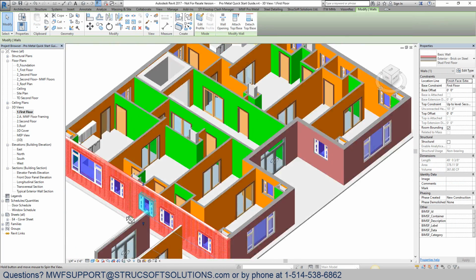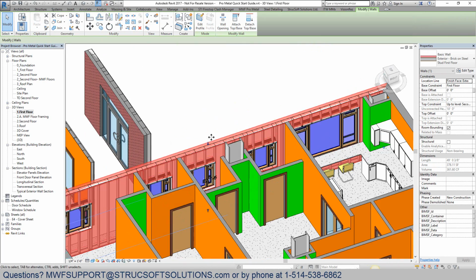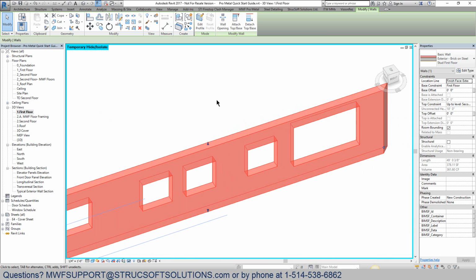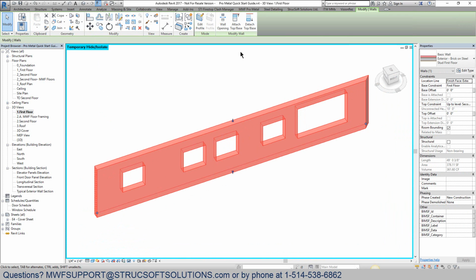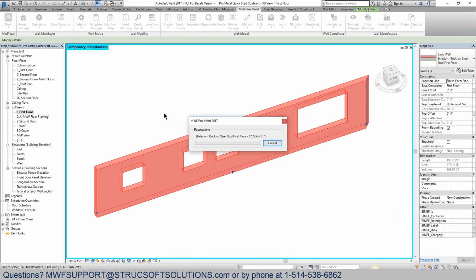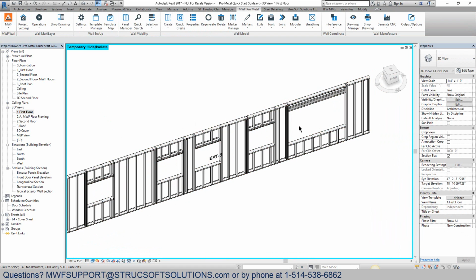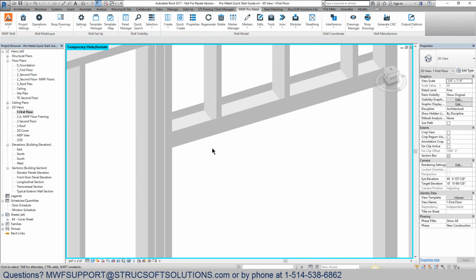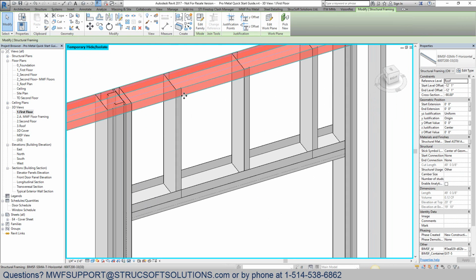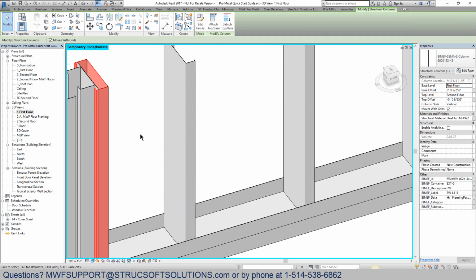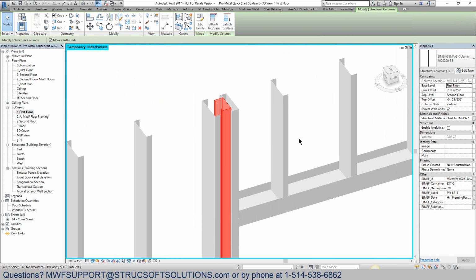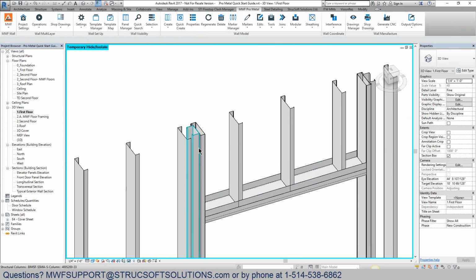Now let's take this exterior panel or exterior wall with the panel in it that we've already created. Let's isolate him again. So it's HI. My wall is isolated. And if I hit regenerate, I get to see my panel comes back into my wall. And if I hide it real quick, I can take a look at my small window. Let me hide my top plate too. There's my 600S. Oh, I can see that my member is being capped inside. Perfect. But I've accidentally used a 400S 200. So we need to update this marker.